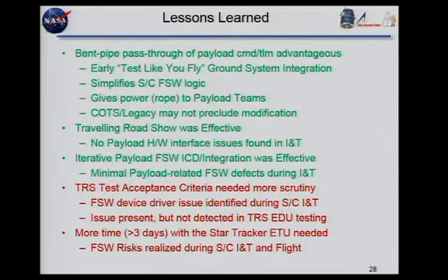Okay, so that's that. I probably covered all these throughout, but this is just a summary of the lessons learned. The bent pipe approach was advantageous. It allowed tests like you fly with the ground system. You're probably all aware that cFE uses CCSDS, so anything you put on the bus can come to telemetry, and commands going up are also in the same format that your ground system sends up.